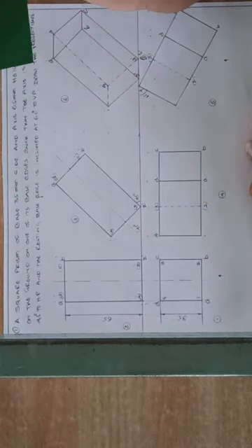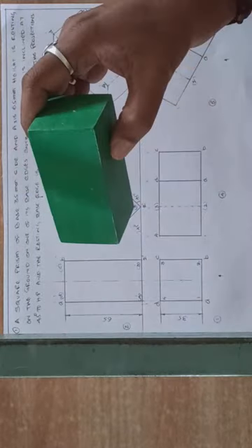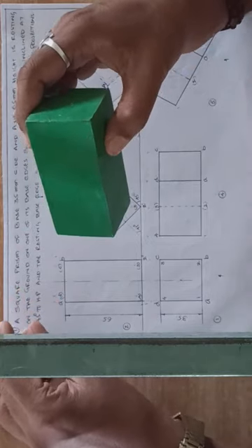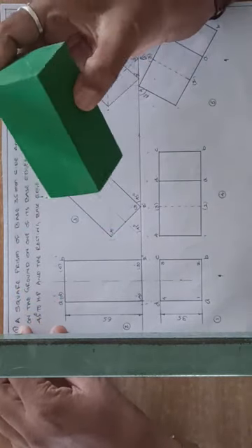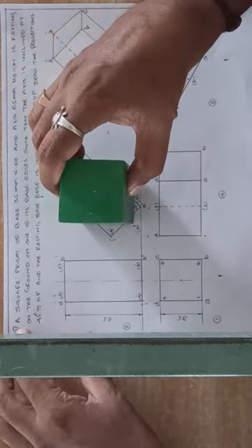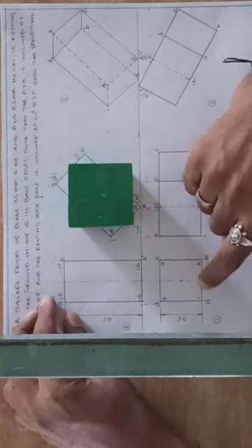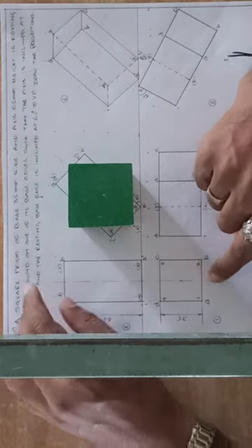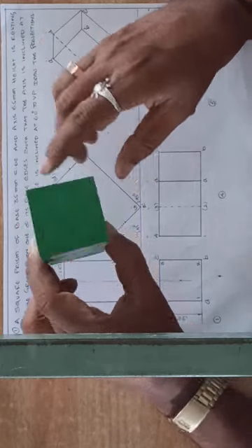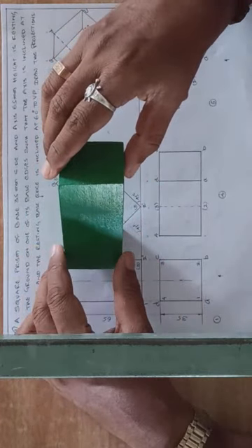First let us say the first condition is the axis is inclined at 45 degrees to HP, like this. So now to start with the drawing, first you should imagine that axis inclination with HP. Before inclination it was perpendicular to HP. So perpendicular to HP means true shape is obtained in top view. So first you have to start the drawing with the top view. Then see the second condition, whether it is resting on its edge or resting on its corner. Here in this problem it is given resting on edge, right.